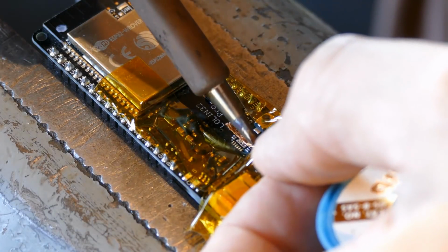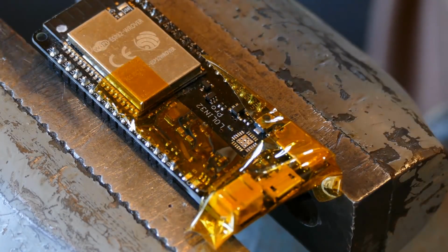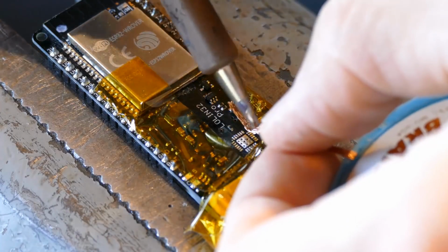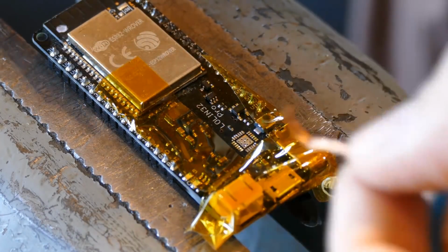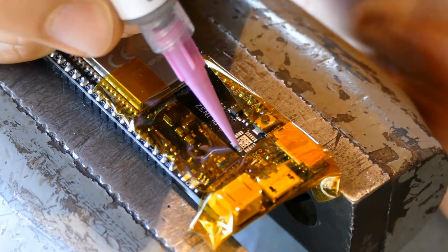After the braid, I'll use superwash to clean up any dirt or flux. A good clean surface always makes for better soldering. Also make sure the PCB is dry so moisture doesn't outgas through the solder paste. Next, solder paste is applied to the pads.